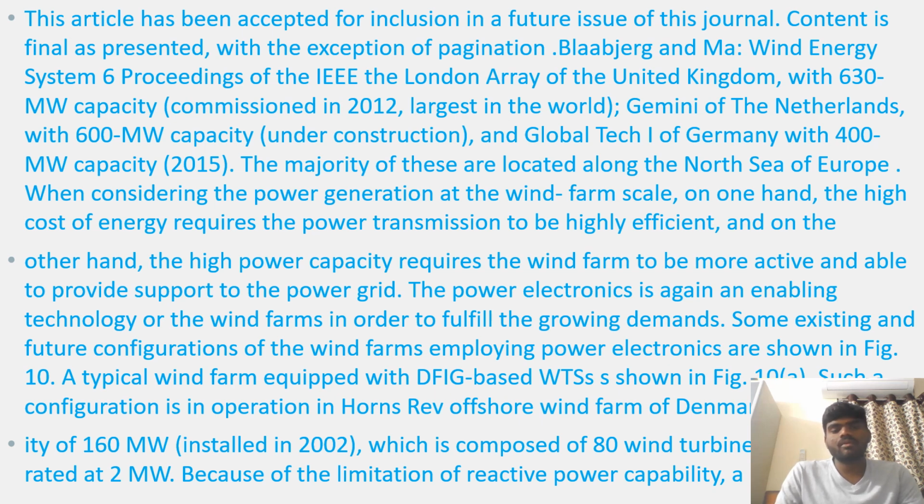On the other hand, the high power capacity requires the wind farm to be more active and able to provide support to the power grid. The power electronics is again an enabling technology for wind farms in order to fulfill the growing demands. Some existing and future configurations of wind farms employing power electronics are shown in the figure, which is composed of 80 wind turbines rated at 2 megawatts, because of the limitation of reactive power capability.